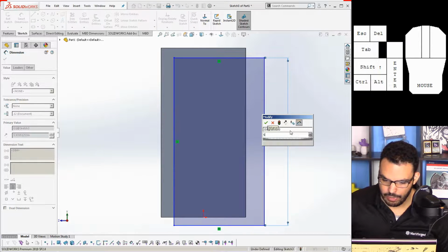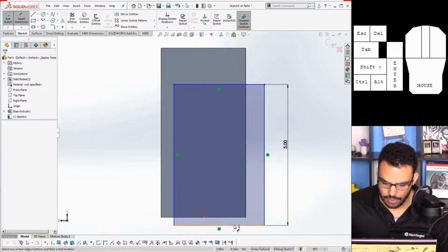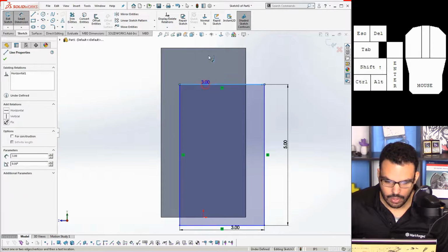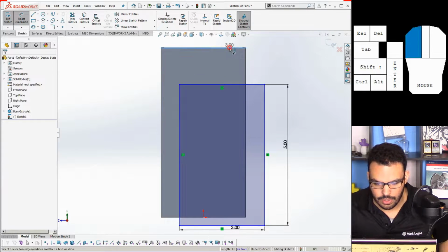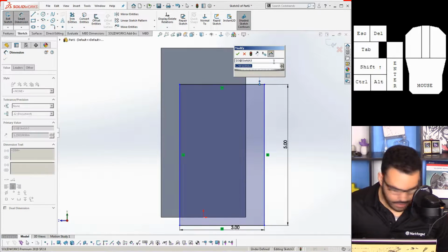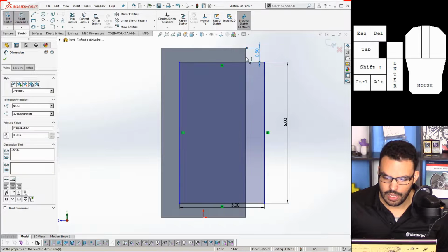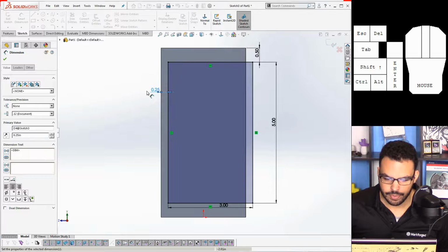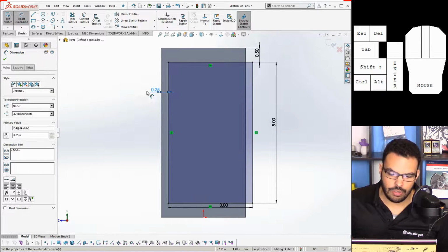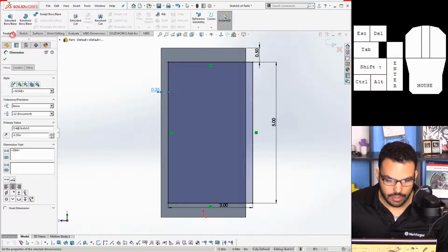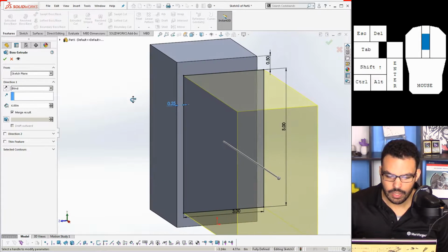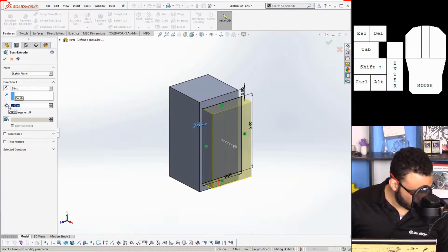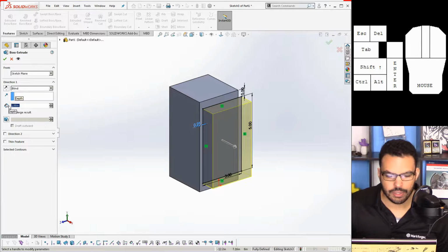The height will be 5. And width is 3. And whoops, I missed there. So I'll just hit cancel and we'll try that. There we go. From there to there is 1/2 inch, and then from here to here is 0.25 of an inch. Alright, so it's fully defined. Yet another boss extrude. And instead of 6 inches out, should be just 1. Let's see. Yep, that is correct.